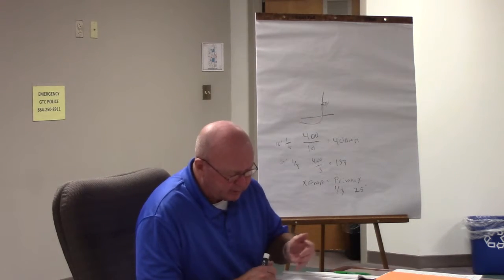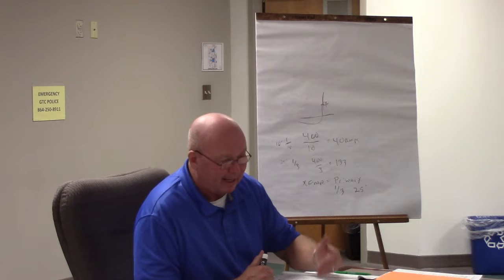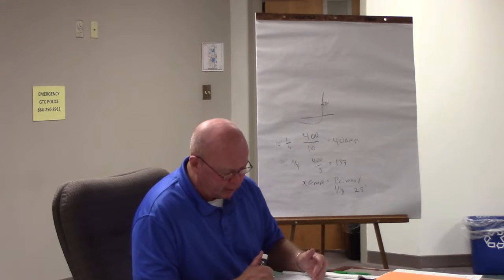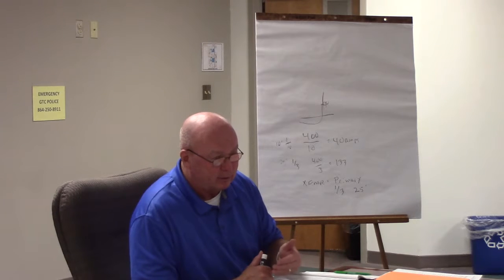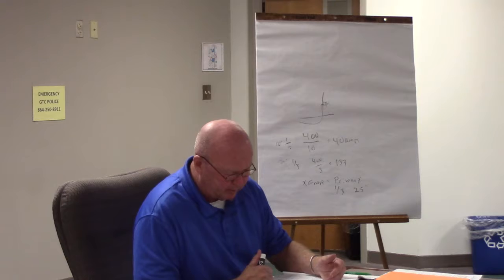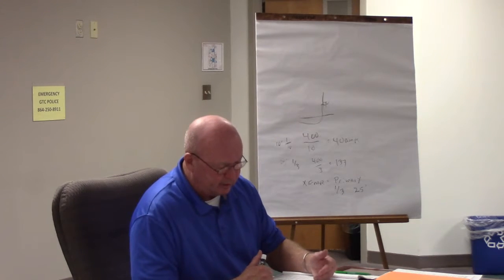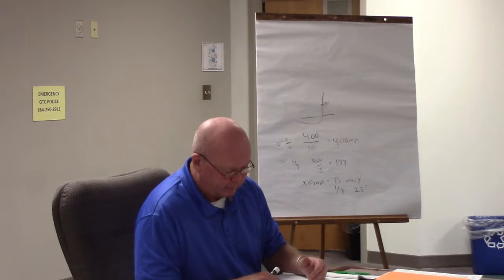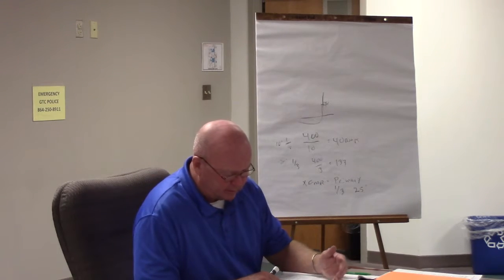Okay. Conductor, let's just read 230.6. Conductors shall be considered outside of the building or other structure under the following conditions. So be outside the building, whether it's installed under not less than 2 inches of concrete. That's outside the building. Is not inside. We're installed within a building or structure in a raceway that is encased in not less than 2 inches of concrete. We're installed in any vault that meets the construction requirements.